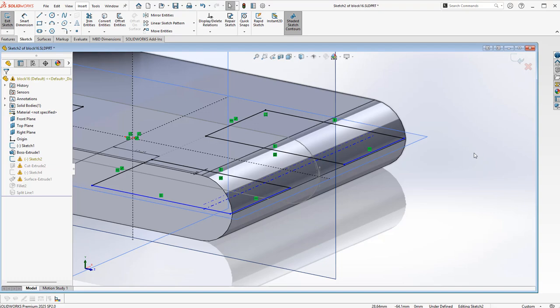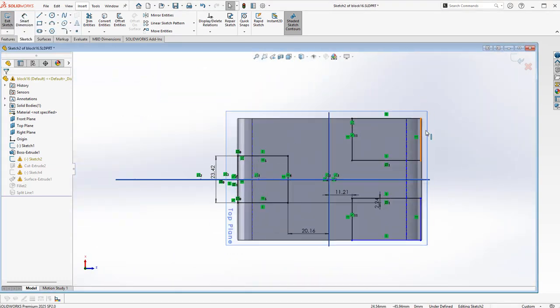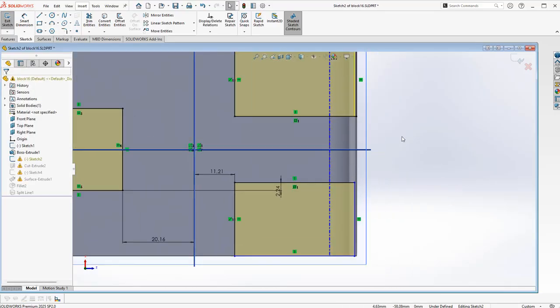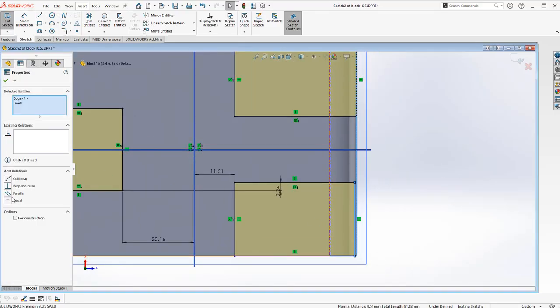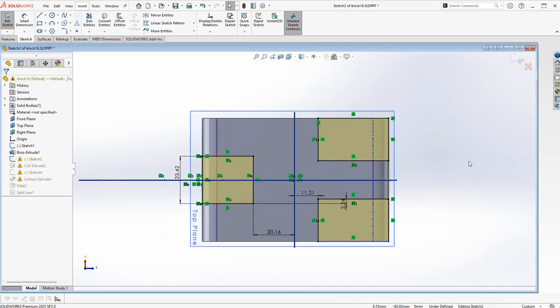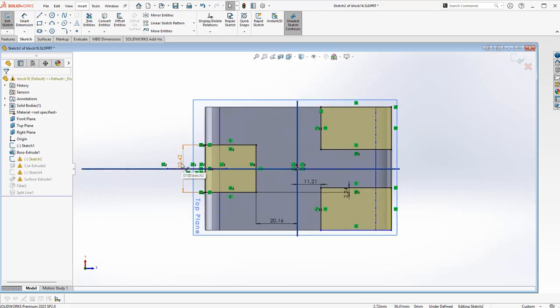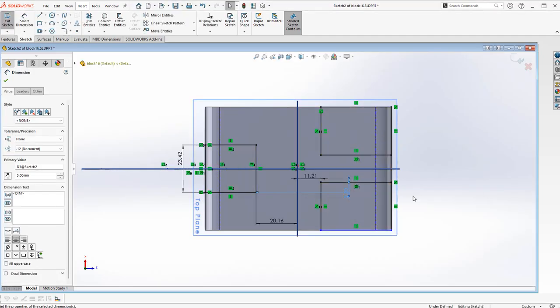Let's just remove them, hit the space bar and square up on my sketch, and then I can reestablish those references. This is the type of thing experts do without thinking or complaining, and necessary if you're going to be considered an expert. All right, so I noticed that I dimensioned symmetry across here. I see. So if I change this to 5, it's symmetric. That makes pretty good sense.